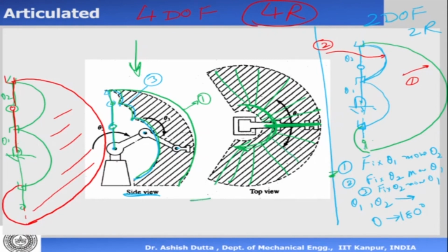Now if I combine the side view and the top view, what will be the shape of the work volume? It will be a spherical part with shapes which are cut inside. It will be a funny spherical kind of shape. It will be a sphere with sections which are cut inside, because of this multiple, like this, and like that. So that will be my sphere, the work volume. Everywhere inside the sphere it can go, anywhere outside it cannot go.